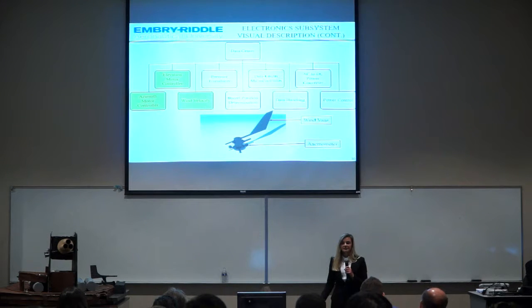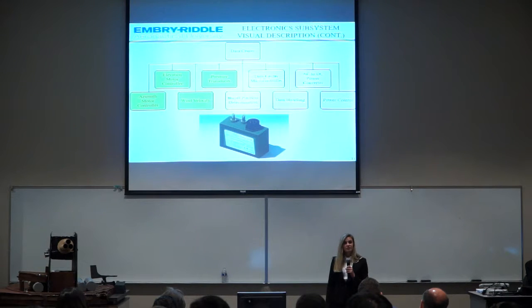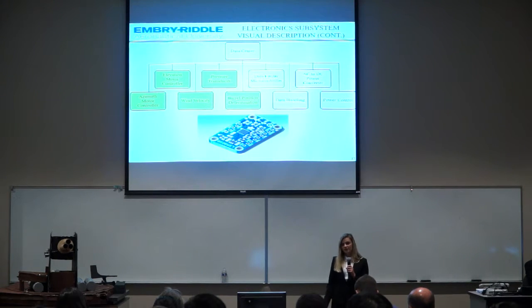The wind velocity sensor measures wind direction with the wind vane and wind speed with the anemometer, and relays it to the data center microcontroller so it can later be used in trajectory analysis. The pressure transducers measure the pressure within each of the 3 auxiliary air tanks independent of each other and relay it to the data center microcontroller as well. The barrel position determination element lies on the front of the barrel positioning, so the launch guidance system, and it locates where the barrel is physically located at that time, both in azimuth and elevation.